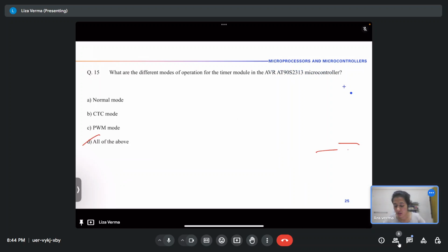Like normal move is whatever move instruction you have done. Then you have MVN, let's say MVN R0 comma R1. What this instruction will do is R0 will get not the value of R1, but the one's complement of R1. So we have these kinds of instructions for ARM also. Very powerful kind of microcontroller.